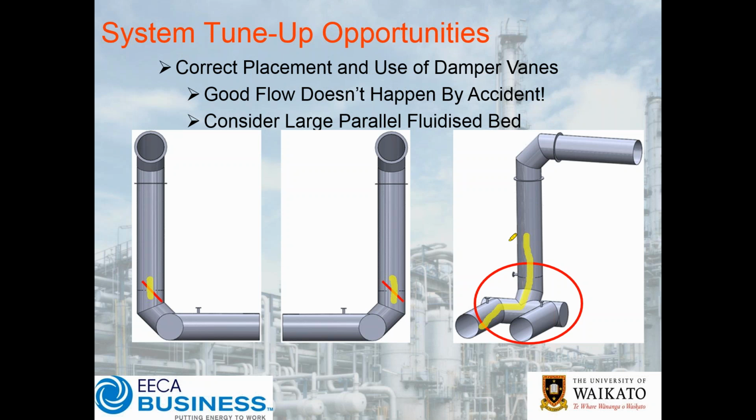And of course what's going to happen here, if we look in plan view, we'll just erase that. In plan view, flow's coming down, doing this and doing this. Of course, if I've got a butterfly valve here in my duct, so let's just have our duct come here like this. If I've got a butterfly valve through here, my flow's actually not going to go on a right angle. It's going to want to come and do this. And so it's going to do this, and it's going to come through here and not through the other side.